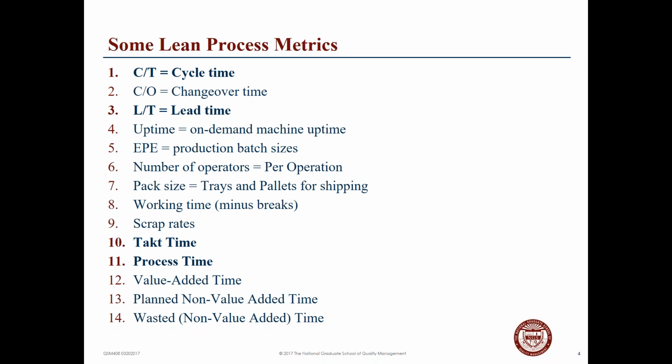Number of operators. A lot of times companies will throw labor at a process to try and keep the rate up. And if all they're doing is tracking parts per hour or parts produced, that's not going to show that the reason they were able to maintain that rate was they added 4 people to the process, thereby adding cost indirectly to the process. So we often measure number of operators per shift.